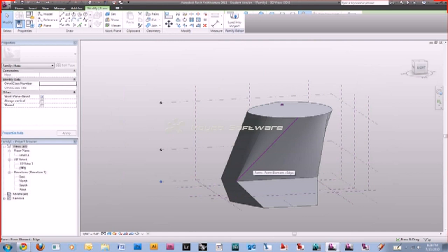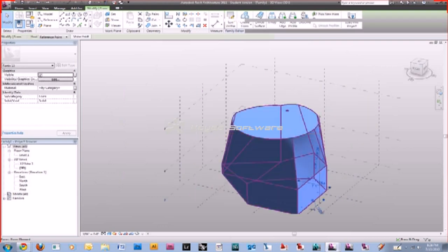Well, if you dissolve something, either you undo it or you recreate it by selecting the same profiles. You can't say stop dissolving. The question is, how do you get out of dissolve? And the answer is you can't get out of dissolve. Once you dissolve, the shape is gone. So you either Control Z or you remake the shape. It deletes all the faces and just leaves you with the line. You're literally dissolving, like imagine putting an acid on something. If you didn't actually want to delete all the sides, you would use the X-ray command, where you're still adjusting the shape itself, versus dissolve, where you're going back to where you started with just the profiles.